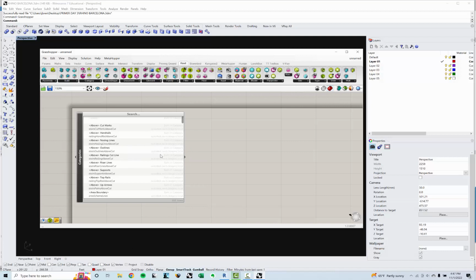So now that this is set up, I'm going to type in a lot of shortcuts here. I actually sometimes click through here to find things, but I usually type in the search by double clicking. If you hold down Control Option and click on an element, it'll show you where it exists. So this categories is in the Revit tab in input right there. So if you're ever curious to see where these things are that I'm clicking on, you hold down Control and Option, or Control Alt, and click on the element.